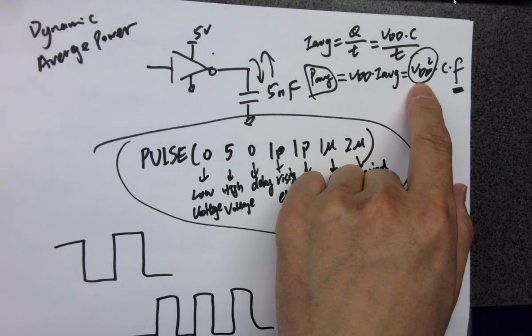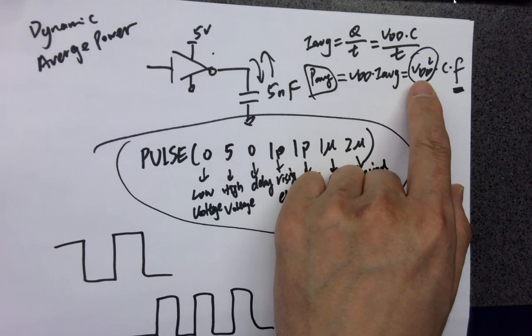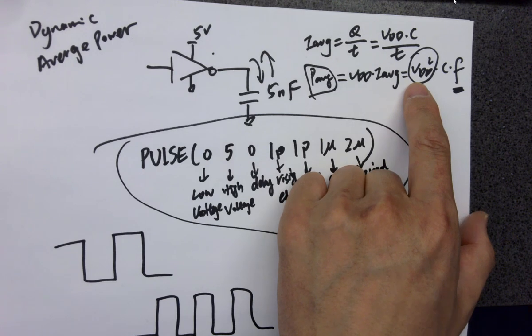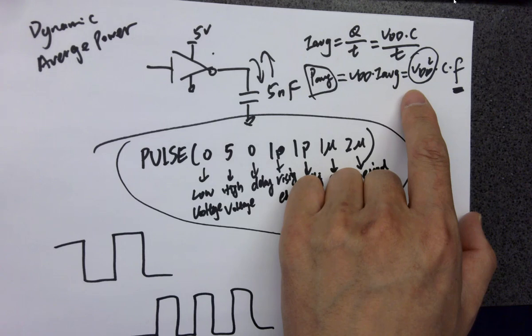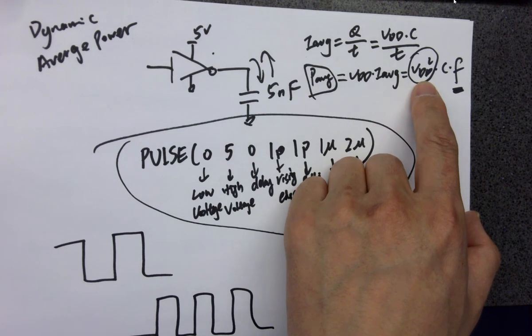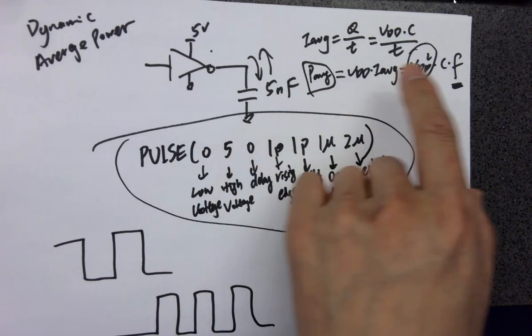The lowest voltage you can use for 180 is actually 1.8. But if you're using 500 nanometer technology, the C5 we have been using for Electric VLSI, the VDD is 5. Compared to that, the VDD is already significantly less, and that's why we want to use a smaller technology, because it reduces the VDD, and so eventually reduces the power consumption.